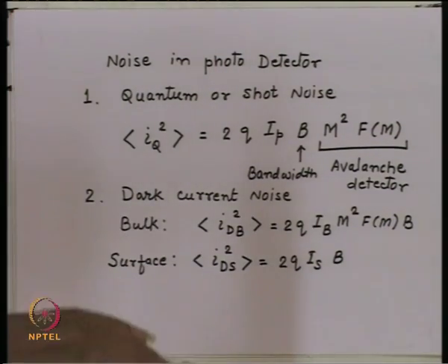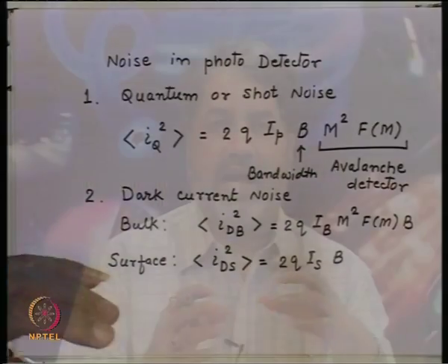So, inside the photodetector, now I have the photocurrents, which could be due to two components. One is due to the signal which is coming from the optical fiber as incident on the detector, and the other one is, even in the absence of this signal, there is some ambient light which might be falling on the detector, or because of thermal excitation, a certain current which will be flowing. These two together essentially would contribute to the noise in the current.